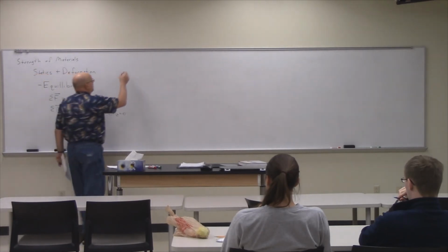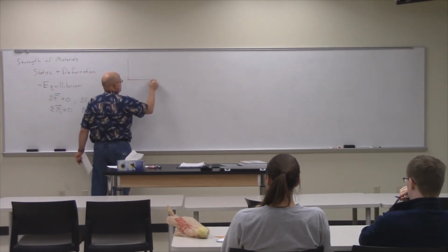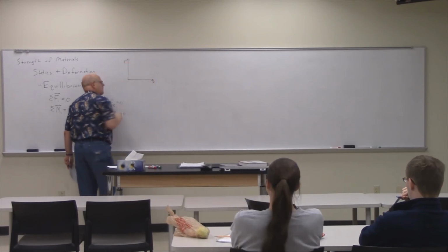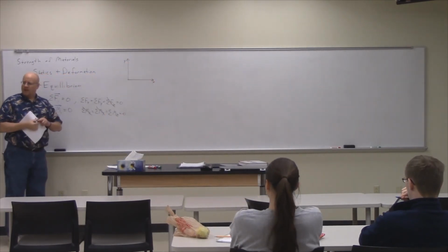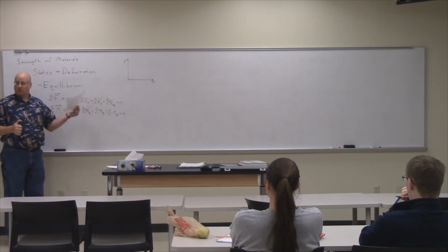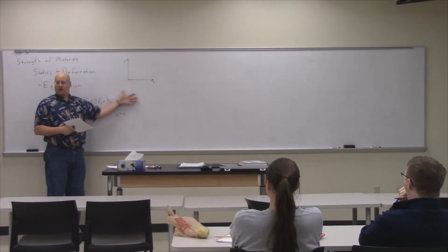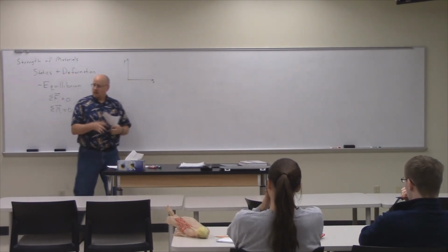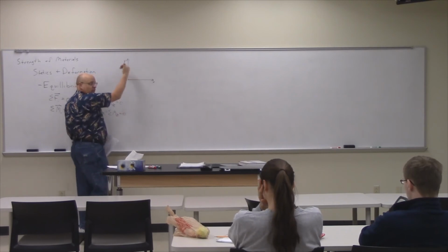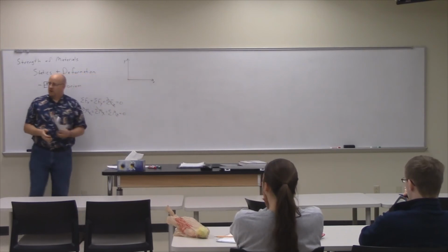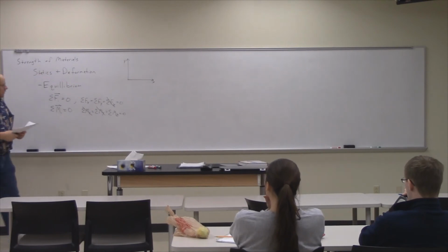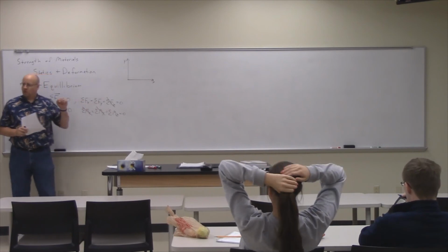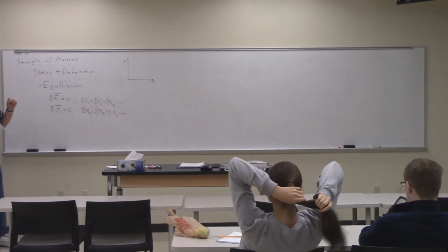Right? Because if my board is my 2 dimensions, then I can have forces in the x, forces in the y, but no forces in the z because it's a coplanar force system. Everything's in one plane. But I can have moments in the z. Right-hand rule. If I have any kind of a force acting out here, the rotation's always going to be about the z in a two-dimensional system. So the 3 pieces that exist in a two-dimensional system are the x, the y, and the z moments. Everybody remembers that, right?